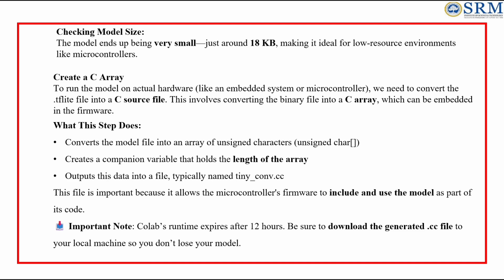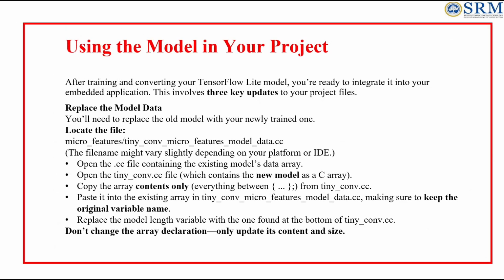Okay. Next, we will see using the model in your project. After training and converting your TensorFlow Lite model, you are ready to integrate it into your embedded application. It involves three key updates. Once training is complete, we need to replace the old model with the newly trained one inside our project files. The process is straightforward. First, locate the file called micro_features_model_data.cc. That exact name may vary depending on your platform or IDE. This file contains the model data array.